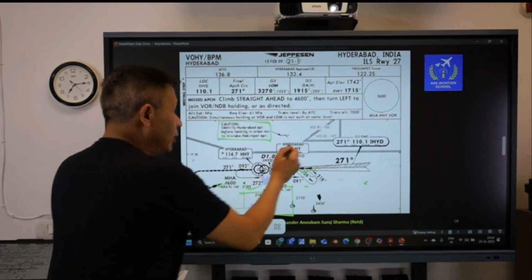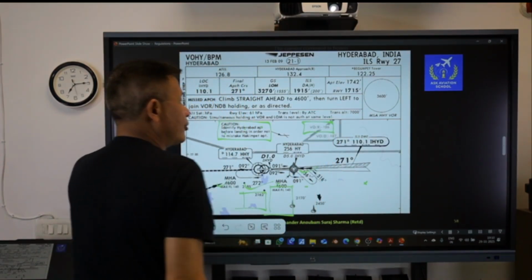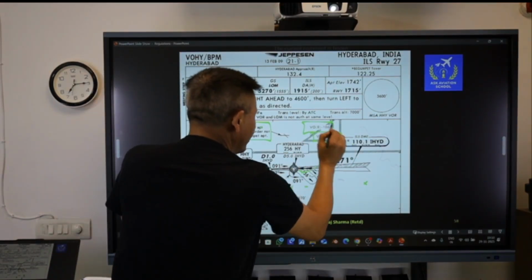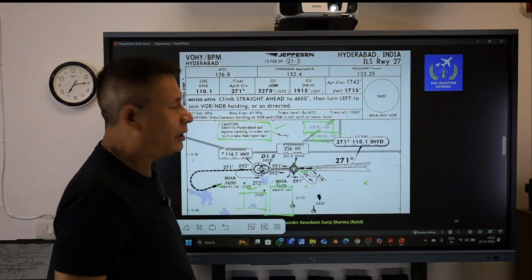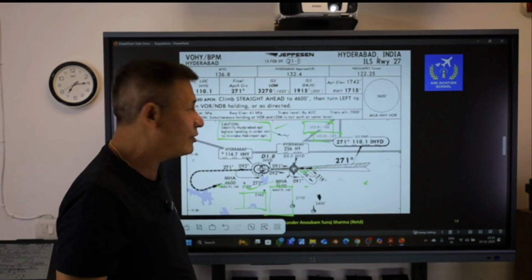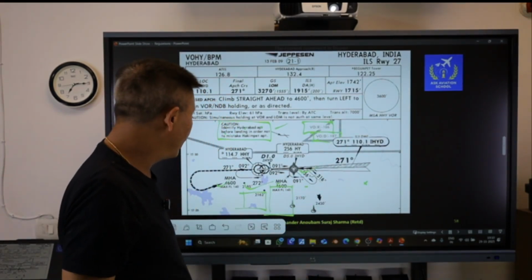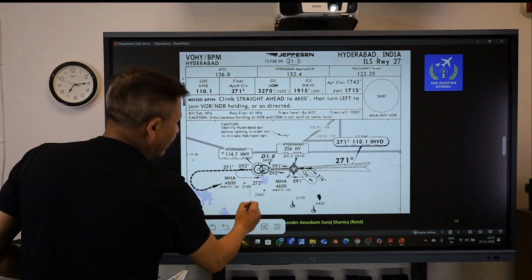And here you have got a couple of zones. Near the VOR, this is a restricted area 186, and the danger area 187 is printed here. This is primarily because of these airfields. Flying into that local flying area without permission is not authorized, so it becomes a restricted area. However, this becomes a danger area. And if you see once again, there are dots here with some numbers printed.